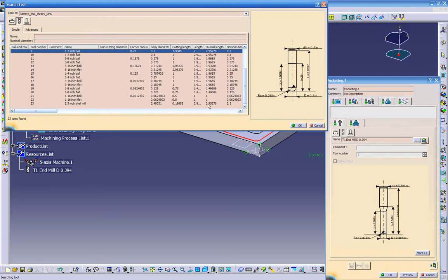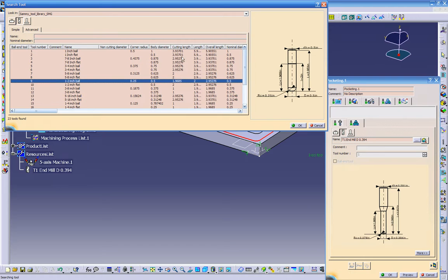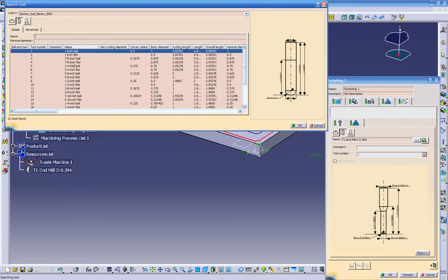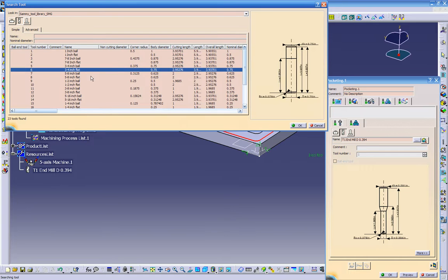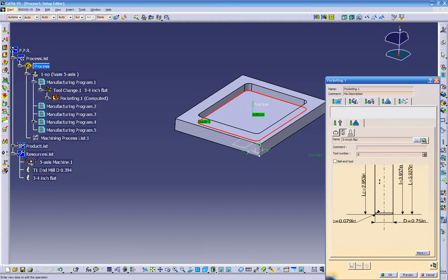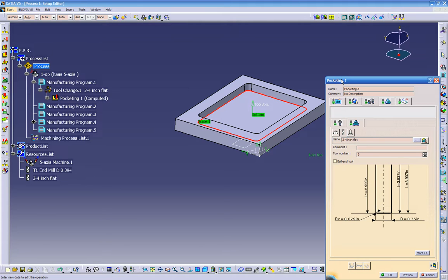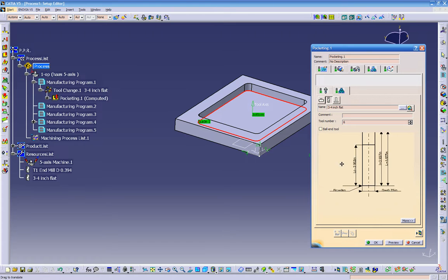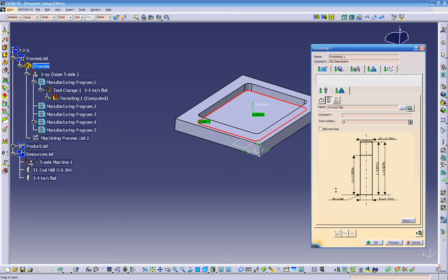This is standard diameters. And for example, let's say we want to choose a 1-inch flat. Let's click on 1-inch. 1-inch bowl. 3/4 flat. Click OK. And you can customize it. Even my operation, even though I said it's a 750, for some reason it puts this radius in here, but you can double click on it and make it 0, make a sharp corner.